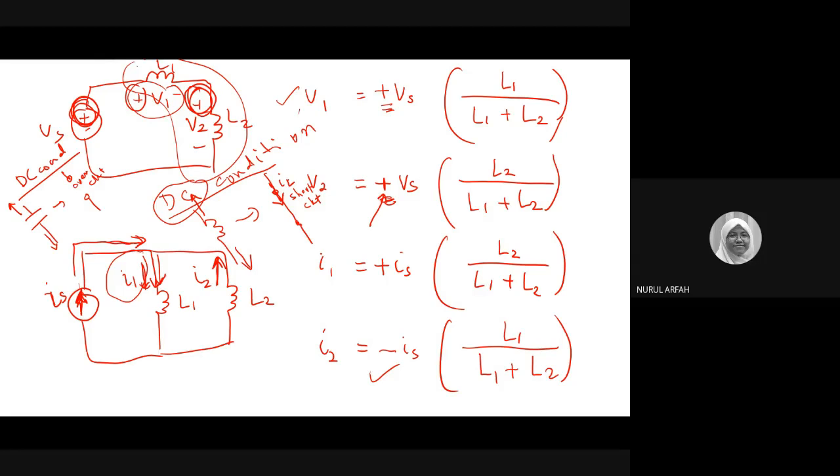But please remember to put the voltage drop, not a voltage source, across that. Physically the capacitor is still there, but under DC condition it will behave like an open circuit with some voltage drop VC across it. So this is very important.